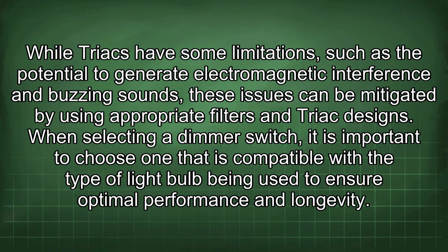While triacs have some limitations, such as the potential to generate electromagnetic interference and buzzing sounds, these issues can be mitigated by using appropriate filters and triac designs. When selecting a dimmer switch, it is important to choose one that is compatible with the type of light bulb being used to ensure optimal performance and longevity.